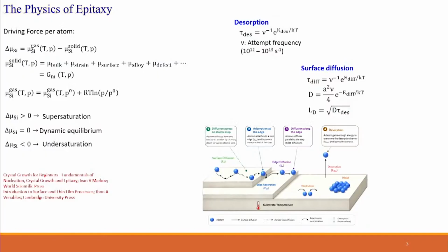If not, I told you it's metastable. It will simply dissolve back. The desorption energy is of the order of 3 to 4 electron volts. The time scales are of the order of milli to microseconds. So an atom gets multiple chances to hop and find the nucleation site. If it cannot, it simply will dissolve.